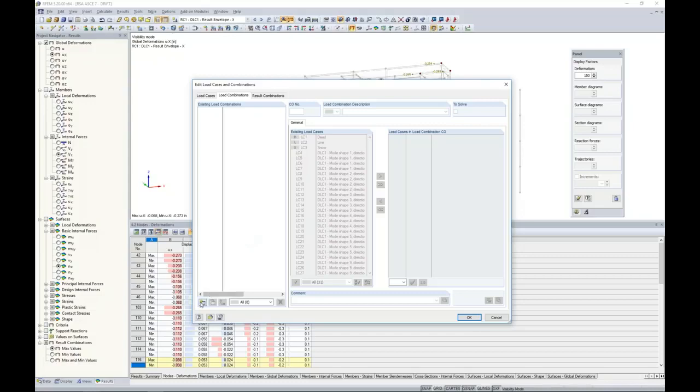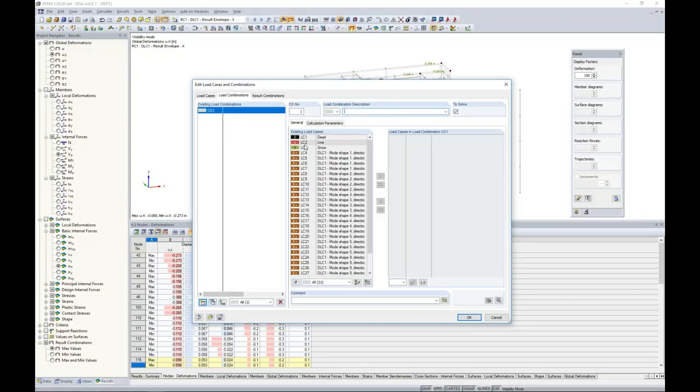If we create a new load combination here, this includes 1.2 dead plus live plus 0.2 snow, and eventually we'll add in our earthquake as well. For these gravity loads only, I change around my load factors to reflect what the code tells us. So 1.2 dead plus live plus 0.2 snow. Now I have this existing load combination with only gravity forces or axial loads.